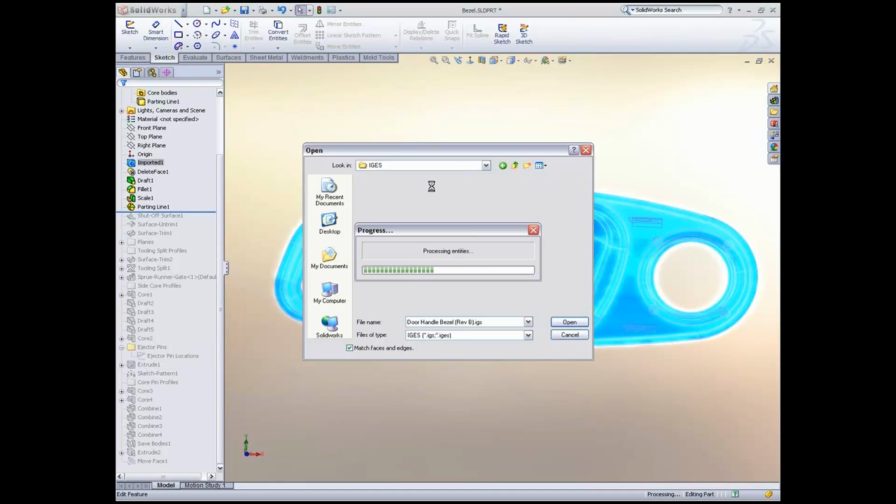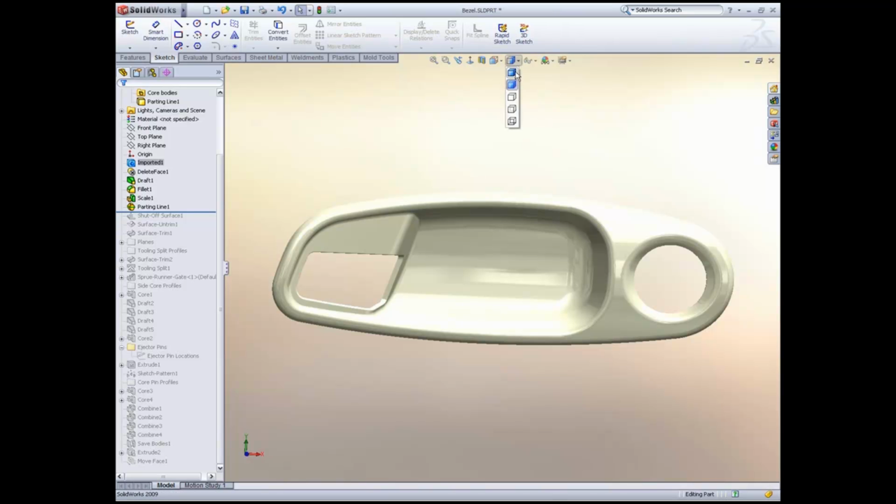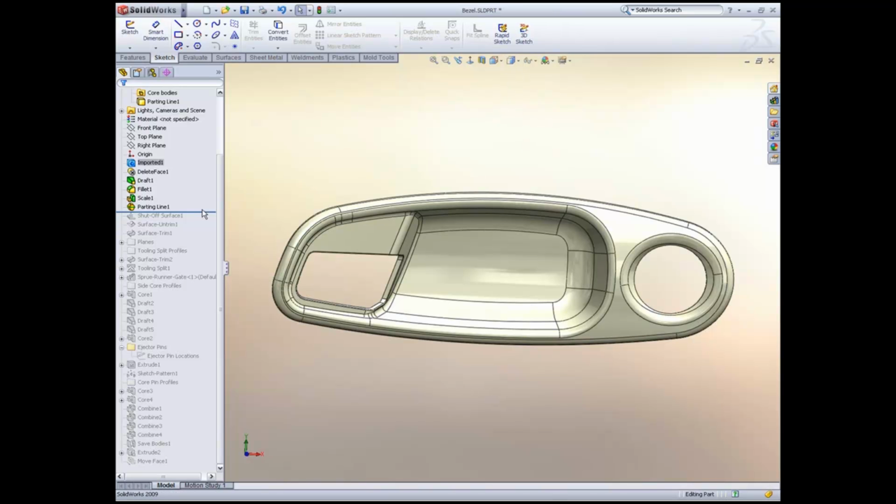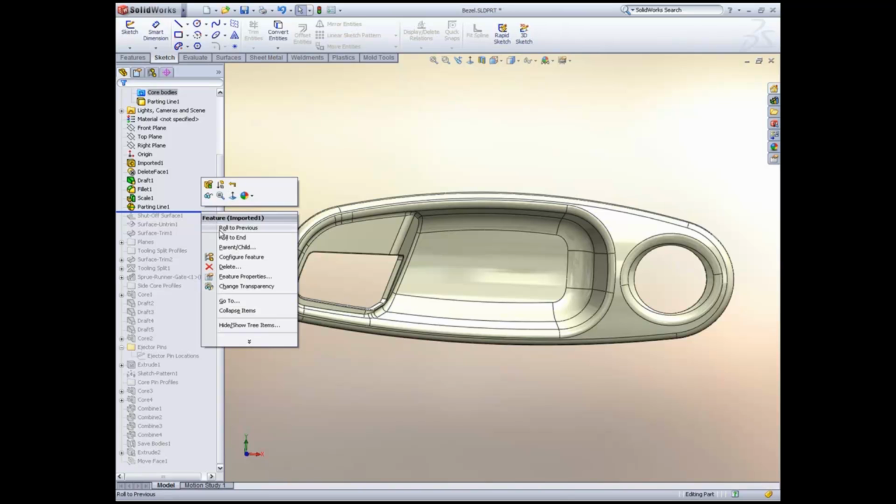If a change conflicts with the previous design and requires a new parting surface or side core, SOLIDWORKS will indicate any potential errors and try its best to rebuild the mold. Problem areas can then be fixed manually until the mold is working as expected. The good news is that you won't have to start from scratch, even with the toughest of design changes. This change in geometry does not affect the split line or the shut-off surfaces, so we're in good shape to let SOLIDWORKS rebuild the rest of the mold features we made earlier.